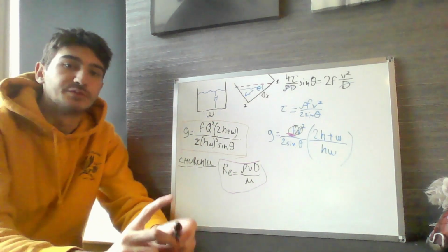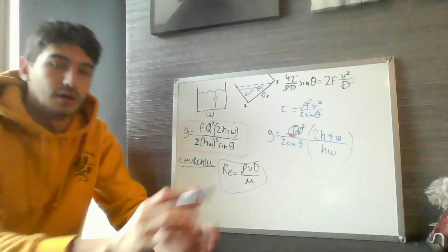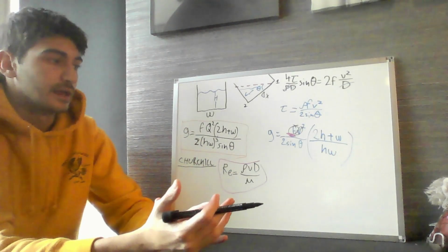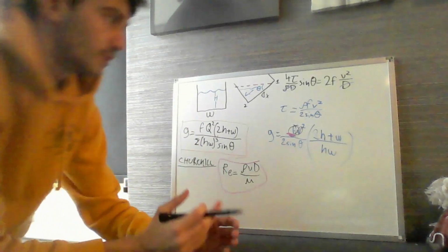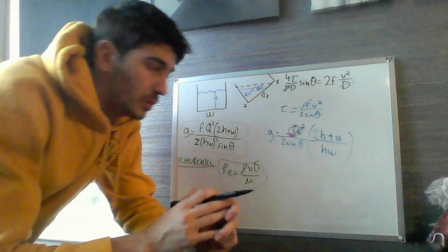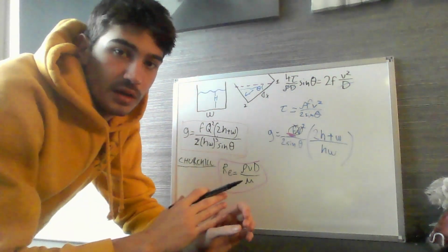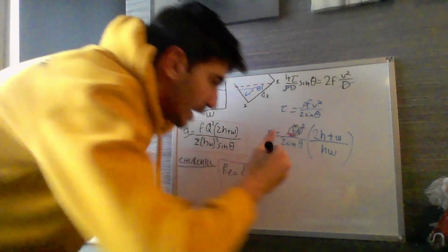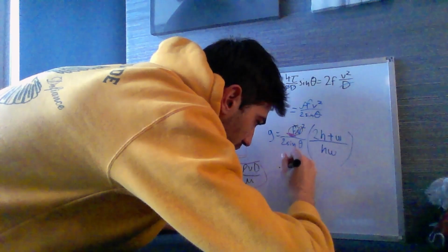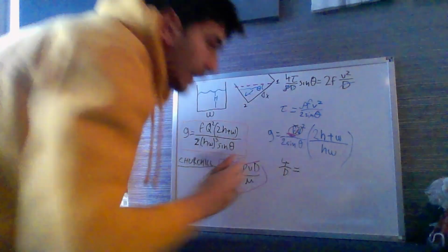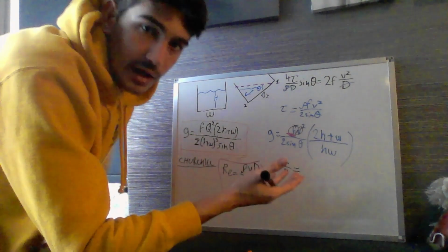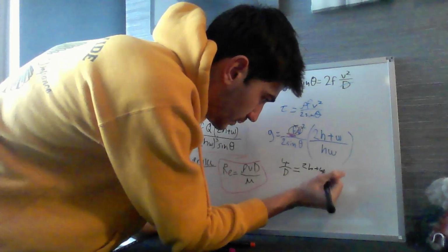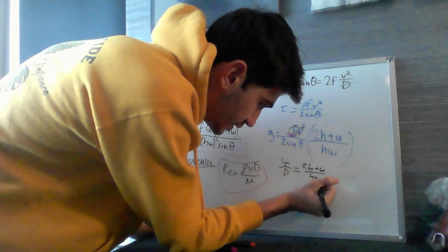What we're going to do is relate it back to our circular aqueduct instance and get an expression for D. So if you may recall what we got for the value of the wetted perimeter to the area for the circular instance, we had 4 over D, correct? And then for the square aqueduct, we have this expression 2H plus W divided by HW.